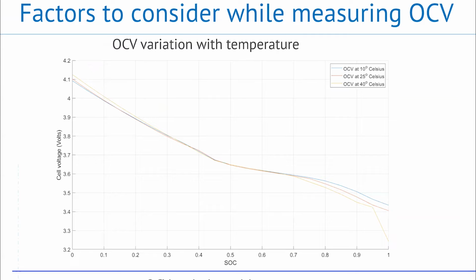So here it dictates one important thing, that your temperature variation, that is to say the OCV variation with temperature, is very important. It has to be considered, and especially battery management systems have to know this at all points in time, because according to this, the terminal voltage also will be calibrated. When you're estimating the resistances and the terminal voltage, predicting some other values within the BMS, the software program, it has to be calibrated according to the temperature, because even the resistances will change.